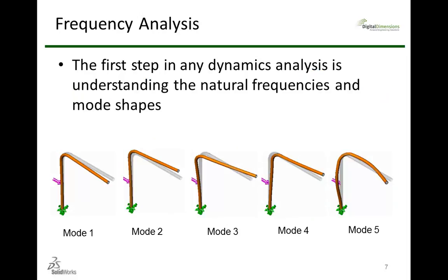Now, the first step in any type of dynamic analysis is to understand the natural frequencies and mode shapes of your structure, because these tell you how your structure is going to deform due to a dynamic load. So let's go into SOLIDWORKS and let's start off by doing a natural frequency simulation on the circuit board.